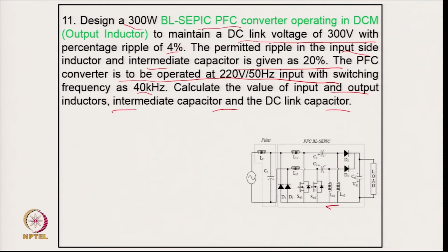So, this is the power factor bridgeless single ended primary inductance converter, and here both the inductors at the input are identical, the capacitors for energy transfer are also identical, and the output inductors are identical. That is different: these inductors are designed for DCM, so that you can apply inherent power factor correction only with the voltage follower approach by controlling the output voltage.